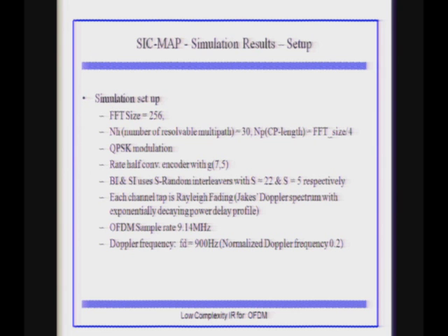What that means is, at the input of the interleaver, say there are 2 symbols, say A and B, and after the interleaving, you won't find the adjacent symbols. You will be finding them at least 22 symbols away from each other. I don't know whether I'm clear there.